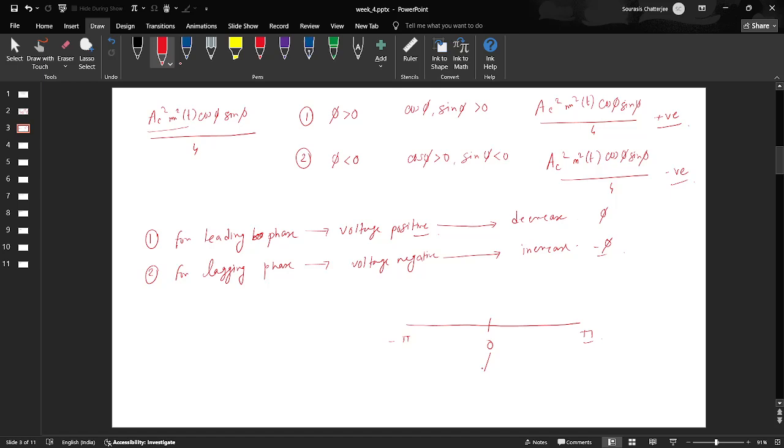Now 0 is the point we want to achieve, the ideal scenario. φ being 0 means the carrier signal generated at the receiver is neither lagging nor leading its counterpart in the transmitter. That means they are synchronized perfectly.